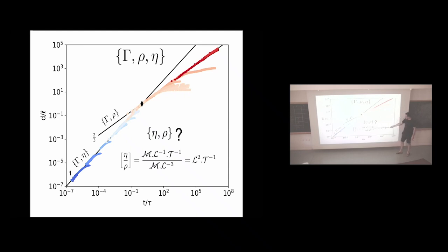Viscosity has these dimensions, the mass cancel out, and what you get is an area per unit time. And so this quantity here is also called the kinematic viscosity, and it's involved in the diffusion of boundary layers.